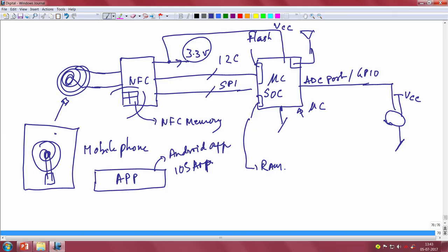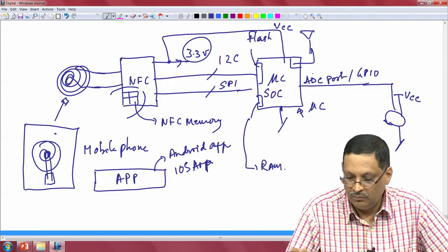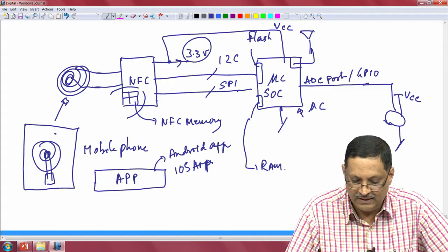Bring a phone close to a piece of equipment which does not have a battery of itself. You power this, you pair it with this coil, and somehow by magic NFC generates an output rail voltage. Connect this rail voltage to this microcontroller, and with this microcontroller power this sensor, read this sensor. Now you can do all kinds of nice things.